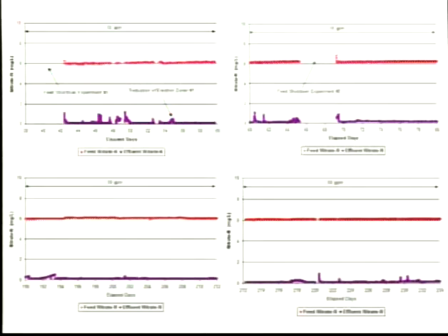But with a fluidized bed reactor, with the recycle or fluidization loop, you're able to maintain that biomass in there if you don't have feed water going in by either supplying a sodium nitrate source or some other electron acceptor. David had mentioned oxygen could possibly be provided, but it's a way to keep the microbes in that system alive and viable. So the data here I just wanted to show you was the continual performance over about 235 days or so, less than certainly the MCL and near non-detect or non-reportable at all times.